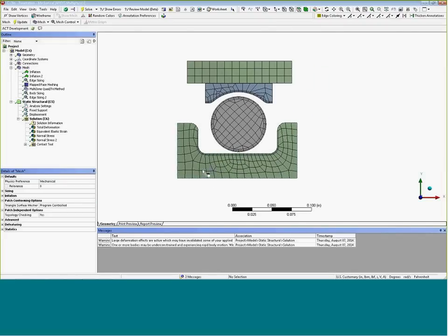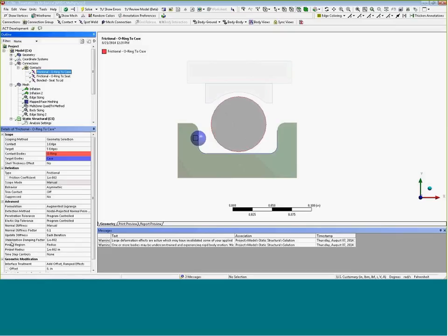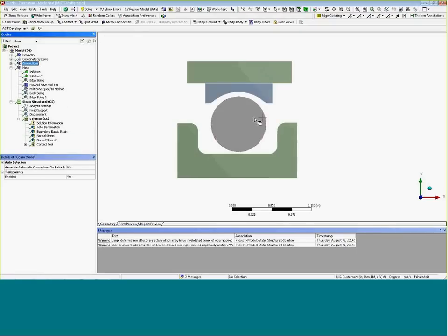because we're taking this part with a displacement, driving it up, and holding this fixed. So there's nothing going on here, but this part initially there's a gap. So there's nothing holding this from moving off in rigid body motion. So we have to do some other things that prevent that rigid body motion. And in this case, on this contact pair, I just used some contact damping to resolve out any of that motion that may occur. So there's little things that you may have to set for the different problems, but it's not really a big deal.